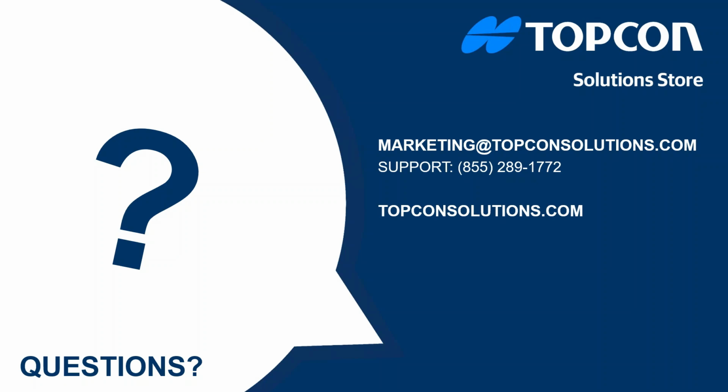Mike, one question here in chat is asking about data shortcuts and whether those can be on the internal server and then brought over to the ACC. It's best to keep all of your data in the ACC collection and start it from the ACC, but I think it could be brought over. You just run into some hiccups with pathing.